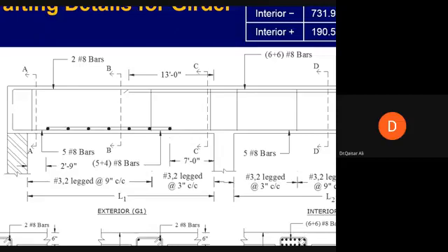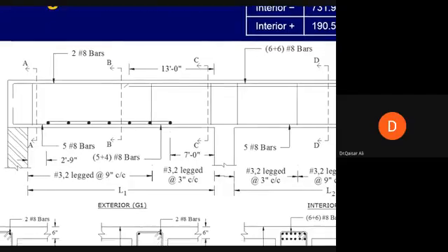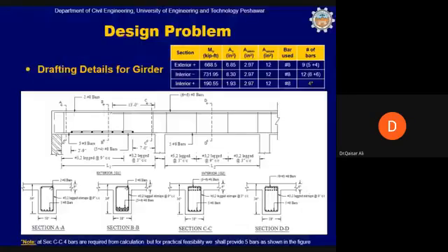And this exact location can be calculated from the equation of the bending moment diagram. The bending moment can be expressed in terms of x, and then these locations can be exactly calculated where this curtailment is required. Again, if I had to design this girder in my design office, I would have never curtailed at this location. I would have curtailed this second layer of reinforcement, but here at this location I would extend this to this support, and to avoid this odd type of curtailment, I would have extended it to here, because I don't need it in this location because of the very small value